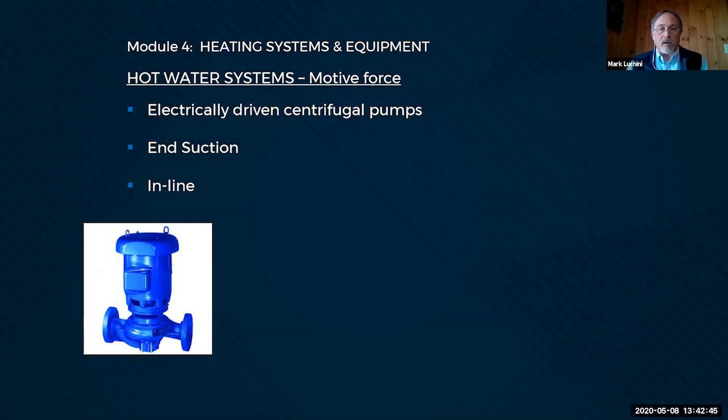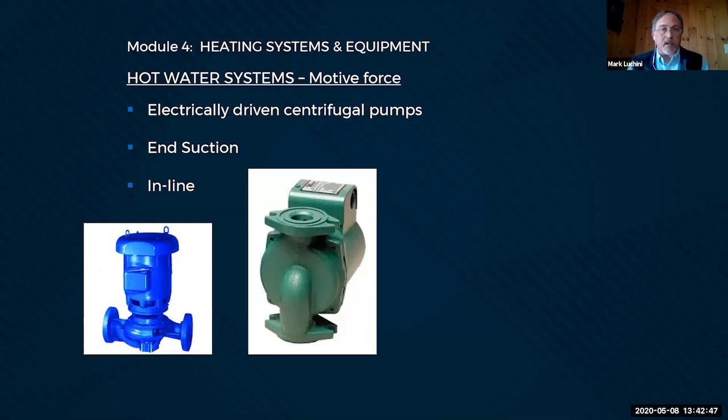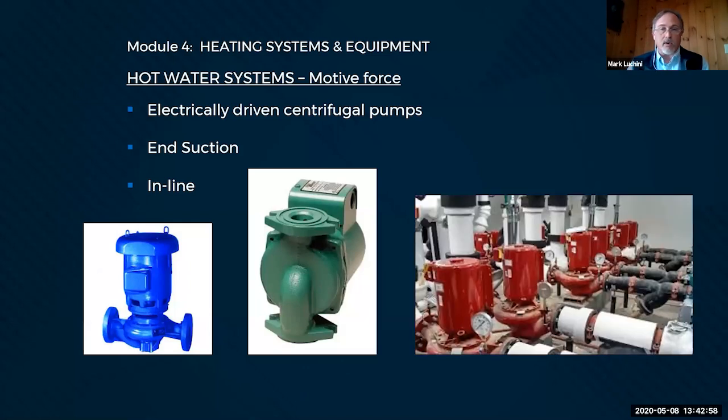Inline pumps are everywhere. If you have a hot water heating system in your house, chances are you've got circulators like this little Taco job here. However, when you're doing some of the larger commercial jobs like we do, you're going to see arrangements like this. This looks to me like chilled water and condenser water. If I had to make a guess, it could be hot water and condenser water.